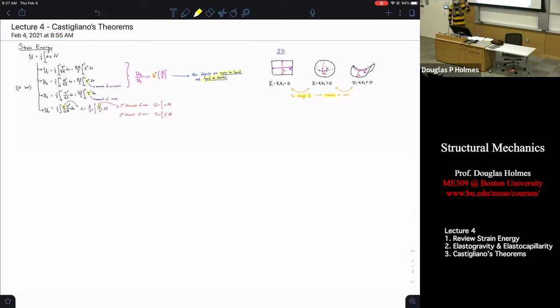But the key is that it's all driven by your intuition. If you know that you have something, add a little bit of curvature in one direction, it makes it stiff, because bending it in a different direction would require it to change its Gaussian curvature, which we know it can't do because it's really expensive to stretch a thin object. That's what your little h squared term there is telling you.